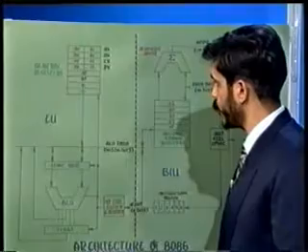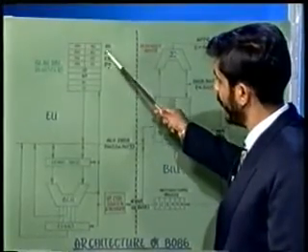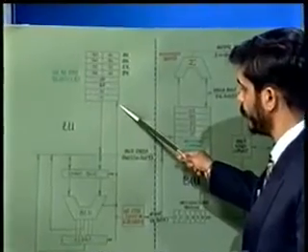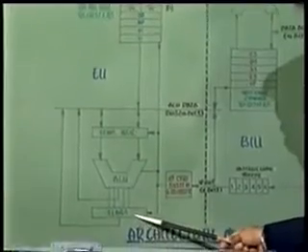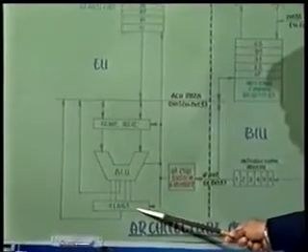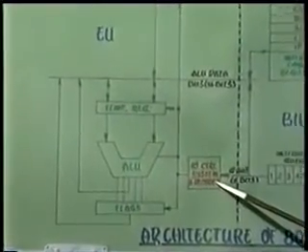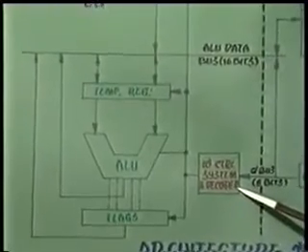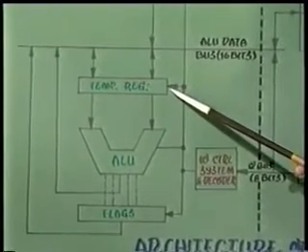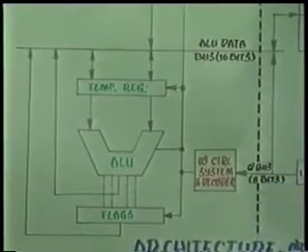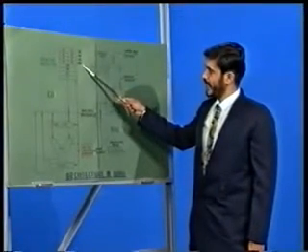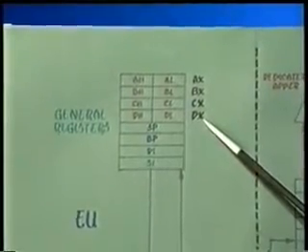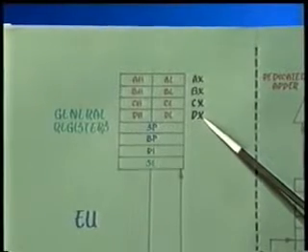Its various constituents are 8 16-bit general registers, an arithmetic and logic unit ALU, the flag register, I/O control system and decoder unit, and temporary registers. AX, BX, CX, and DX constitute the general purpose registers in 8086.